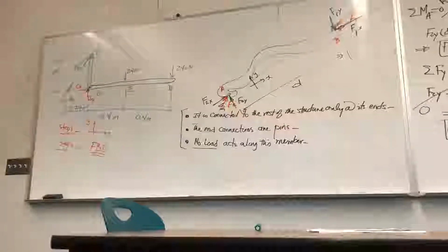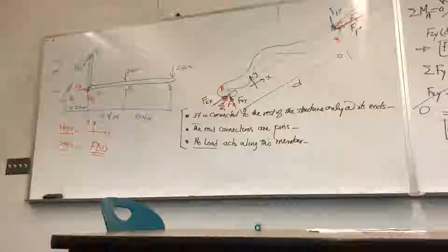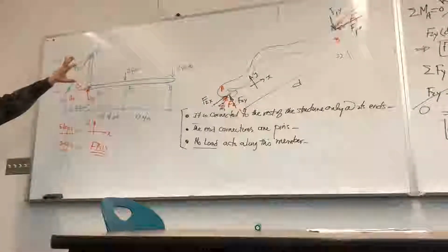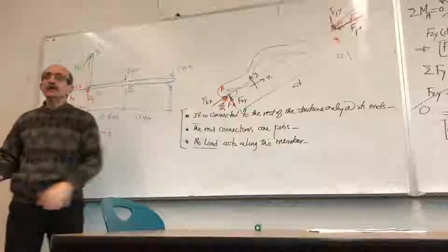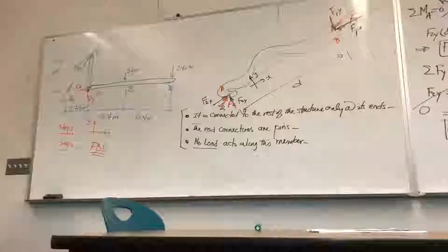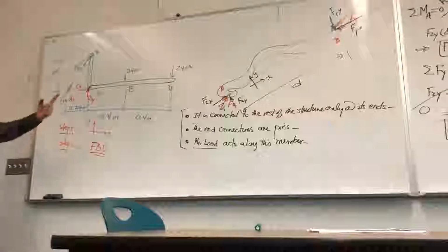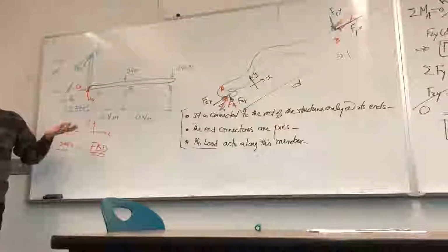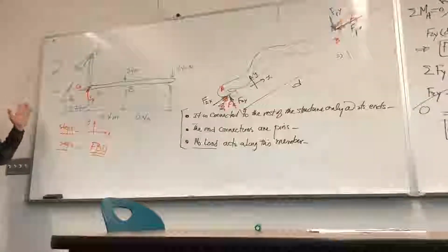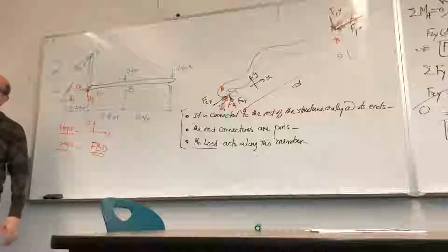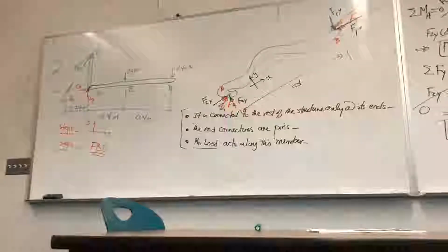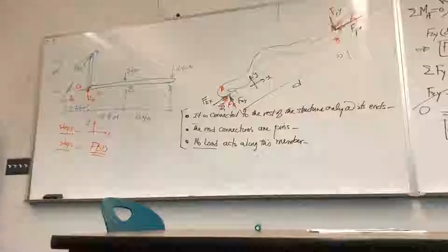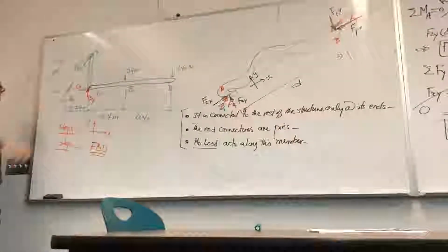And there's no moment applied, just the force? Just a force. If you remove this piece, based on what we discussed, it represents only a single force that acts along the line connecting the two ends. If this was a straight member, obviously it would be along the member, but it doesn't have to be. Regardless of the shape, as long as the two ends are pinned, this force acts along a straight line connecting these two ends, and these two forces are the same.